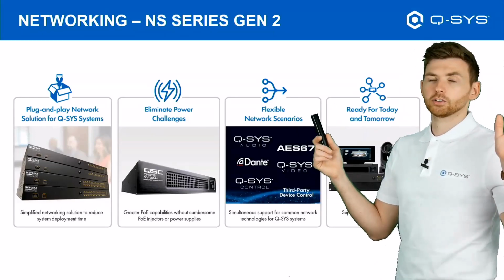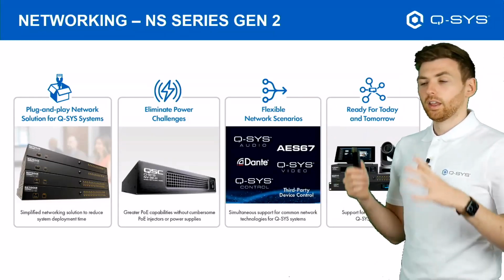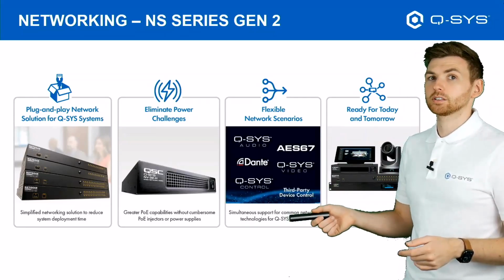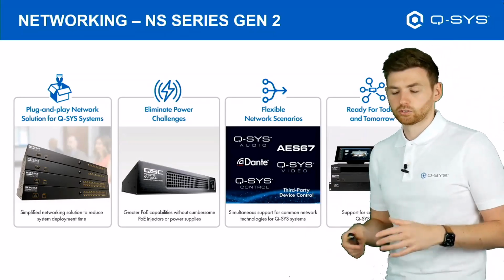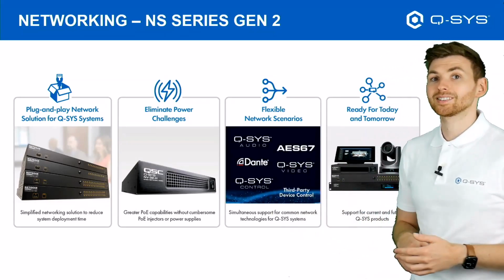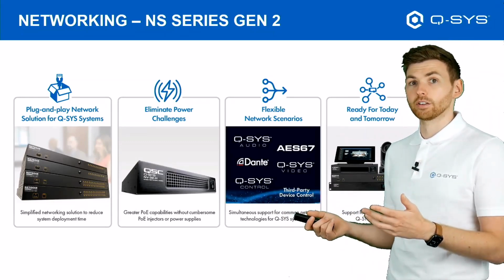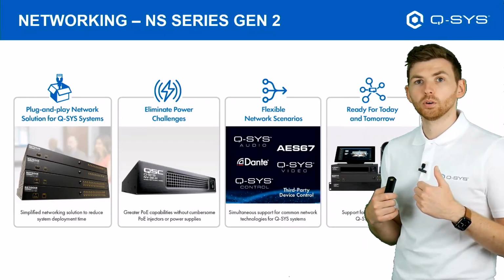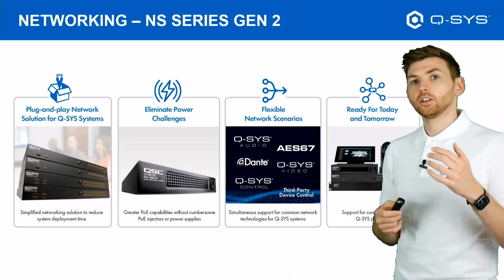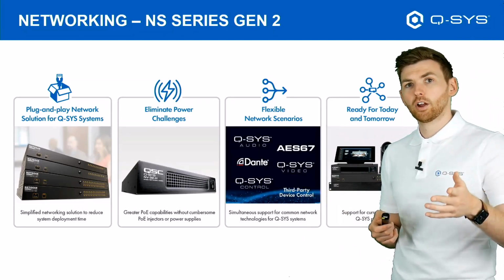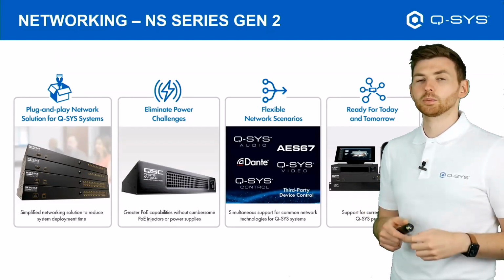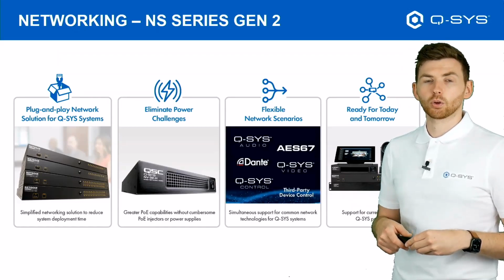You don't have to worry about the switch. You can just connect them up. If you have multiple switches, then all you really need to do is give them unique IP addresses. You don't need to change the configuration. So this is designed for small to medium dedicated AV network deployments. And the cool thing is that if it doesn't work for any reason, you can just call up Q-SYS support. This is a supported Q-SYS product like any other Q-SYS product. And Netgear also have a good support team of their own. Other switch manufacturers, your mileage may vary when you call up and ask them very specific questions about AV deployment.